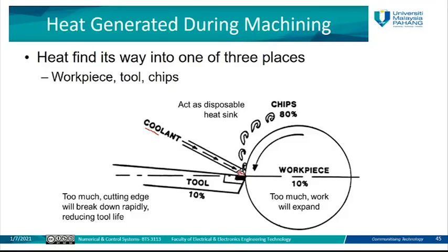In the CNC machine, during the coding, when we change the tools, for example, as you can see in the example for the linear profiling, before the operation with tool number one, we have the coolant on.